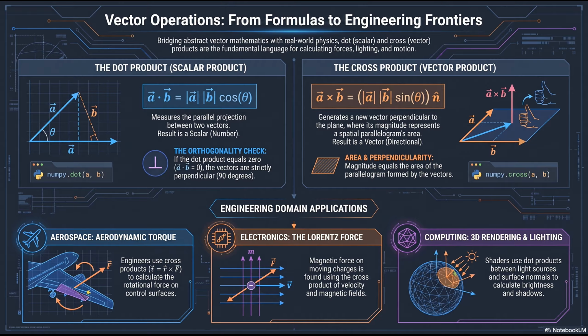And phasors are essentially rotating vectors that track the peaks and valleys of those electrical waves over time. And frequently, the voltage wave and the current wave do not perfectly synchronize. They are slightly out of phase. So by treating these electrical waves as vectors, engineers capture the cosine of the phase angle difference. Exactly. Just like the dot product measures the parallel shadow of two forces on a physical path, this calculates how much the voltage and current are actually aligning in time to deliver real, usable power to your household appliances. It measures the mathematical alignment of electricity itself. That's so poetic. It really is.